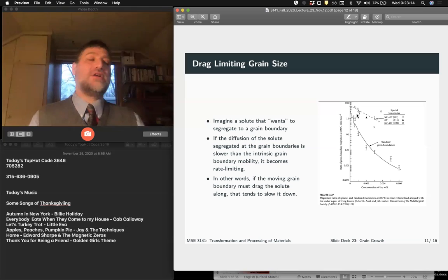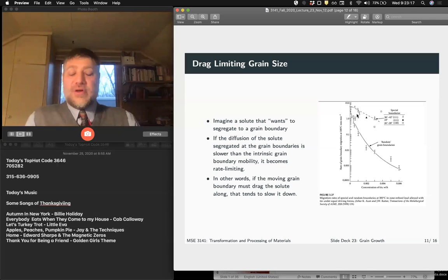So this is a really important strategy for alloying. For those of you who take the physical metallurgy class, either from me or Professor Fraser, whoever is teaching it in the future, we'll spend a lot of time talking about grain refiners. And there are 2 types of grain refiners: those that enhance recrystallization, meaning nucleation of new grains, and those that essentially prevent grain growth, right?